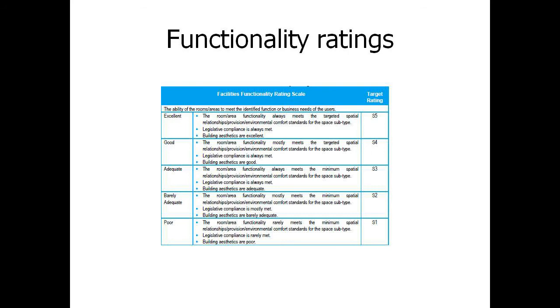As I mentioned earlier, we might also consider other types of ratings or gradings as we're doing a building audit, and one of them might be the functionality rating, along with the strategic rating, the SI rating too. The functionality rating, I must say, is quite often hard to determine. It's quite qualitative. I always sort of say it's like the taste of chocolate. Someone might really enjoy the taste and someone else might not. And that's sometimes the case here with functionality.